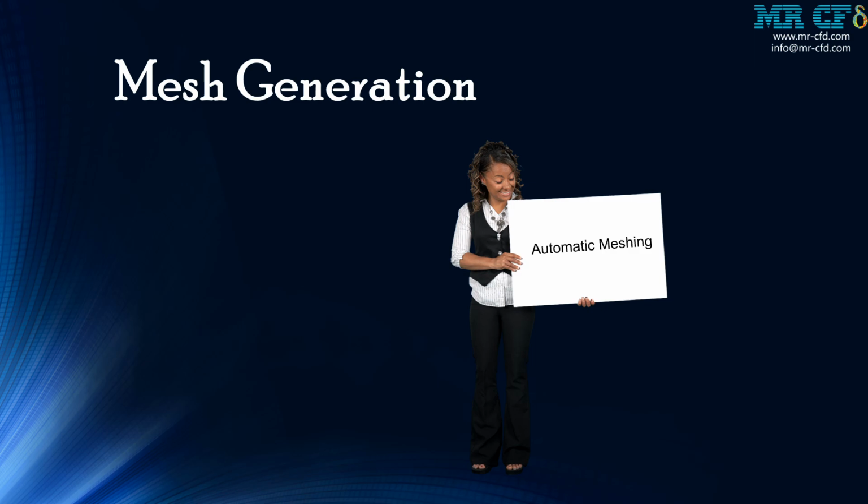The software uses a voxel-based mesh, similar to 3D pixels. This allows for incredibly fast mesh generation and updating, which is key to the real-time simulation capability. While you have less control over the mesh compared to traditional tools, the automatic approach is perfect for rapid design exploration.